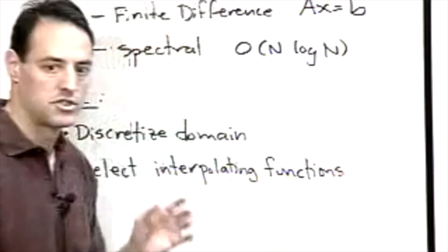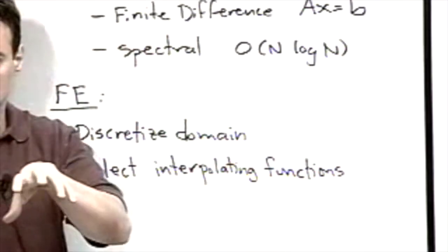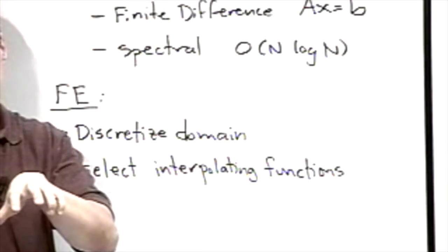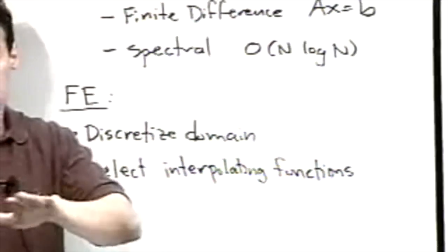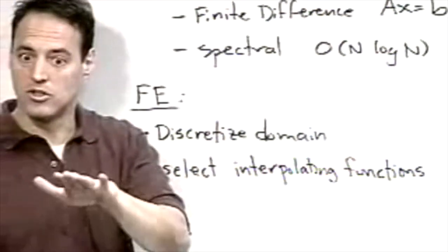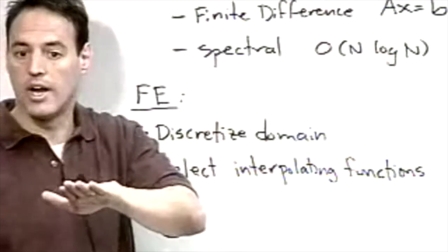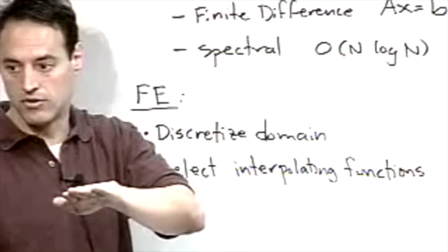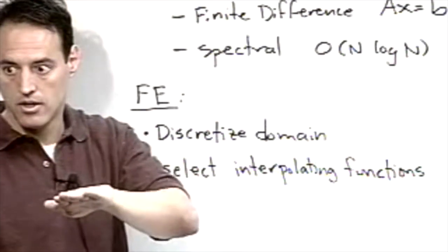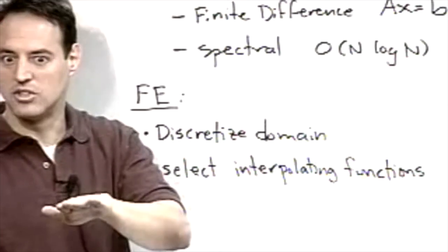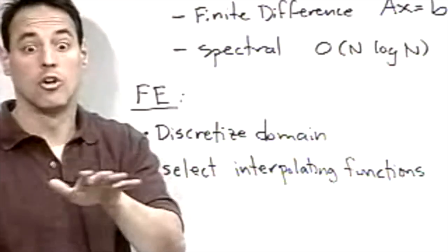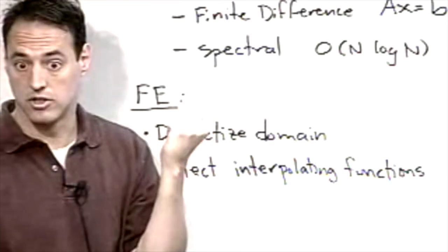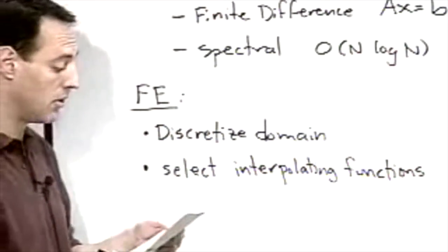So what I showed over there was these patches of triangle. And so that's one interpolation of what the solution is doing. I'm saying on this little area, I'm approximating the solution with this triangle, with some value in that triangle. Of course the solution isn't quite that, but I'm going to interpolate the values according to whatever function I choose in there. And we'll talk about how to build that.